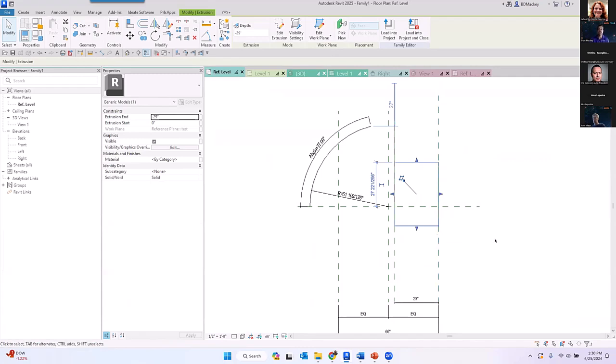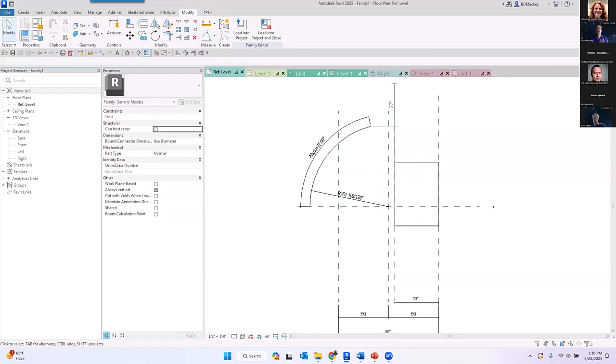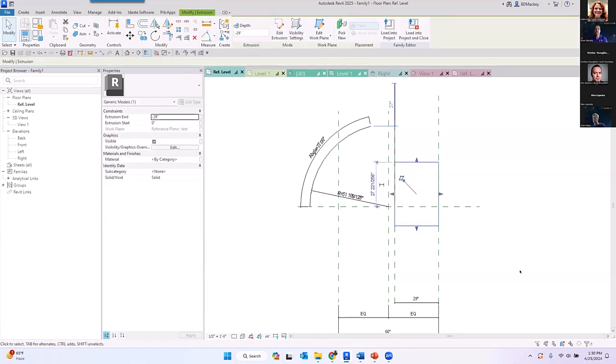I have not tested this in a few years, but I kept doing it, like, man. I would go into Photoshop and mirror my image and bring that mirrored image back in as my rendering image. I kept having to do that every time I did a TV. I'm like, this is ridiculous, there's got to be something better. That's when I started realizing that directionality doesn't only affect the placement of families, but it could possibly affect the rendering image that comes in.